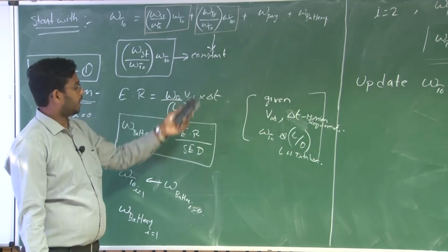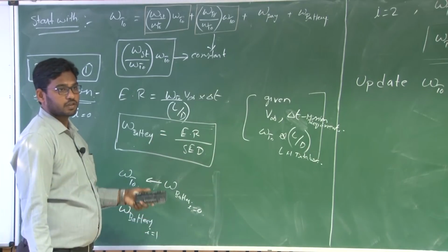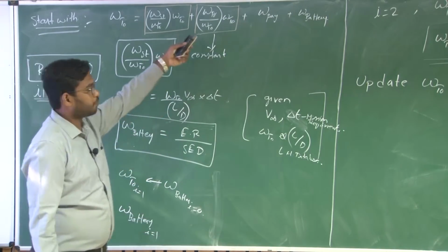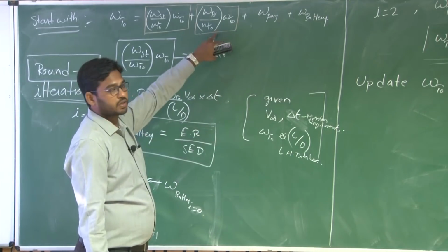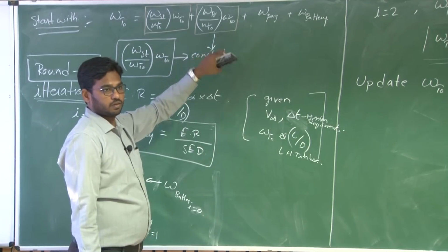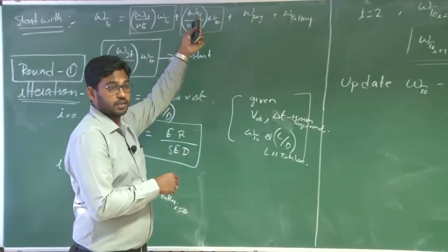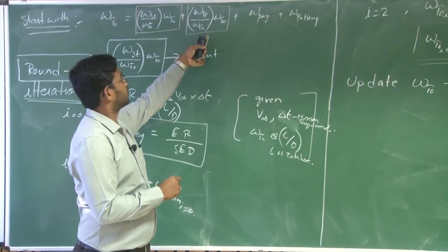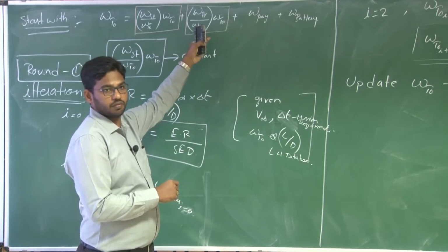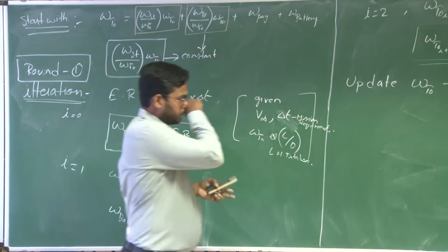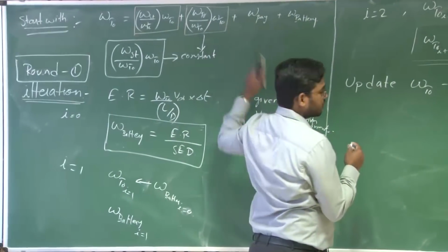This you can figure out by calculating the power requirement during various phases, or the maximum power requirement, and select a power plant that delivers this required maximum power at 50% of its operating power, right? After considering all efficiencies, this should deliver the required maximum power at around 40 to 60% of its operating power, or the maximum operating power.